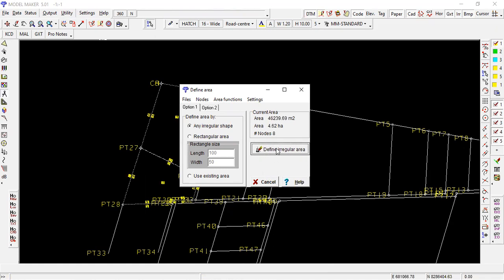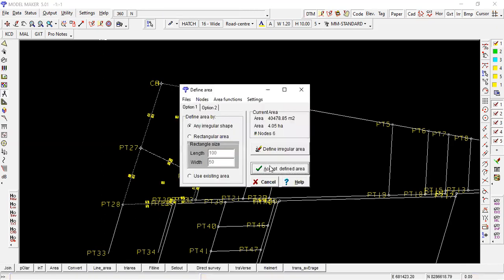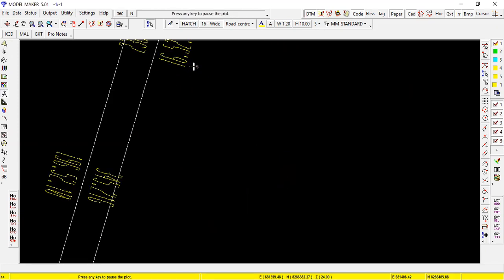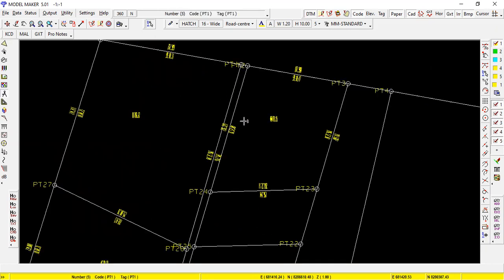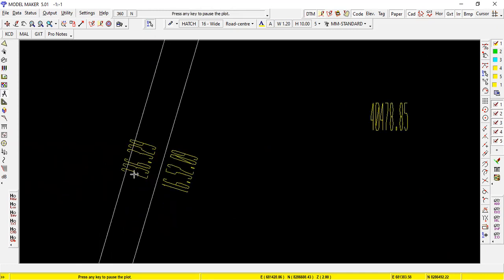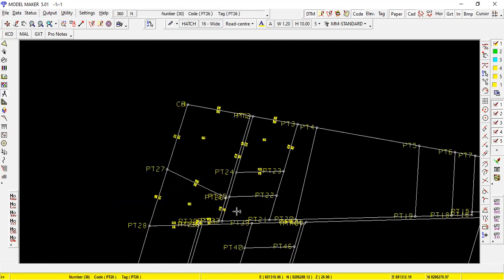And again, I can click on define, then go on to the next boundary, the next parcel, and I do that again, and I accept. And I go to the next one. You can see as we are moving, there are parameters which are showing. So this is the direction, that's 16 degrees, 52 minutes, 9 seconds. Then the length is 236.39. Yeah, so it's as easy as that.